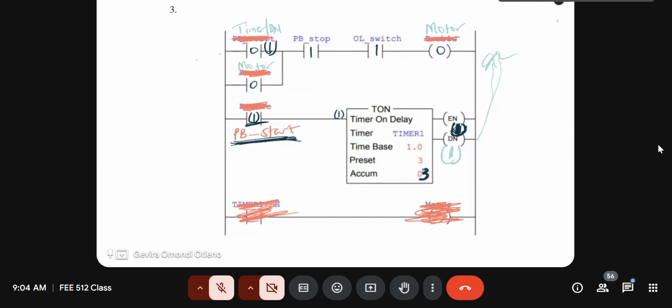But truth be told, I have also looked at this before when I was studying timers. And I was like, the enable bit is always connected on the output rail as well. But if you think about it, what function does it usually perform there? I usually see none, because with the timer we are always interested in reaching the preset time. Then we activate the done bit.